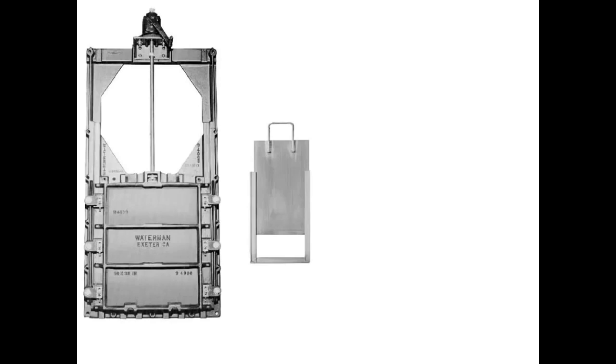And for that reason, when gates get to be much larger than that, there would be some sort of a crank on the top, oftentimes an electric motor, to try and lift the gate. And this is a very substantial gate. Waterman is sort of the dominant player in making underflow gates, and it's amazing once somebody dominates the market like this how sometimes difficult it is to get a gate for a project that you're working on.